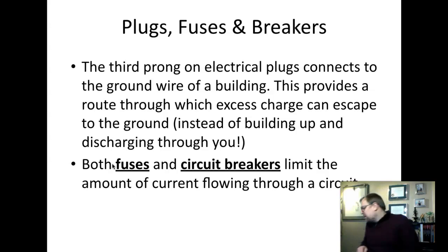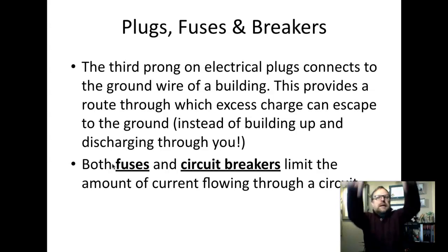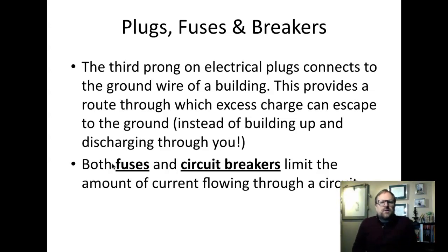So if you have a 3-prong device, and I'm looking for one around me, but everything's plugged in behind my computer right now, so I can't really show it to you. That third prong, not the 2 flat ones at the top, but the third circular one, is the one that is going to prevent a buildup of charge on you. If you break those off, and some people do, you are removing a safety device from that particular cord or whatever it is you're using. So be cautious with doing that, because it could have serious effects if there's an issue with your electricity.